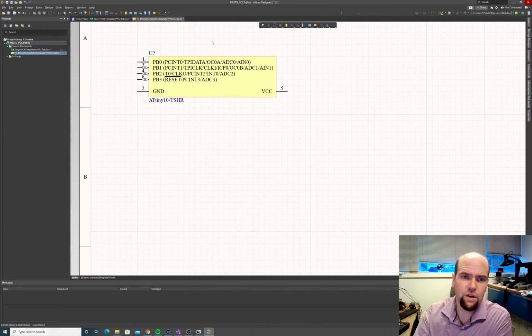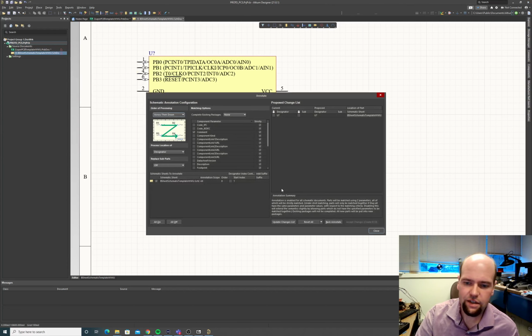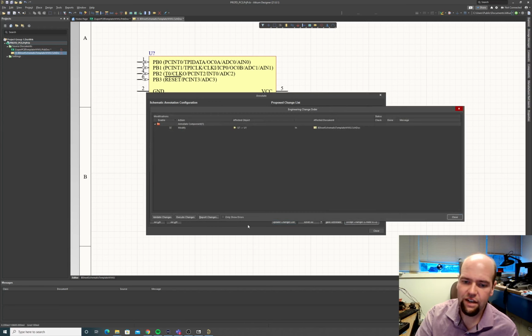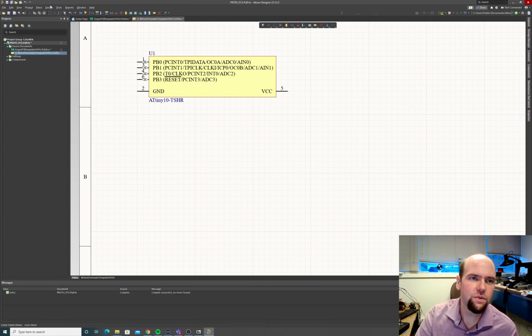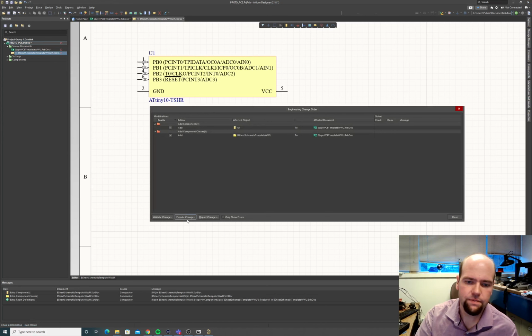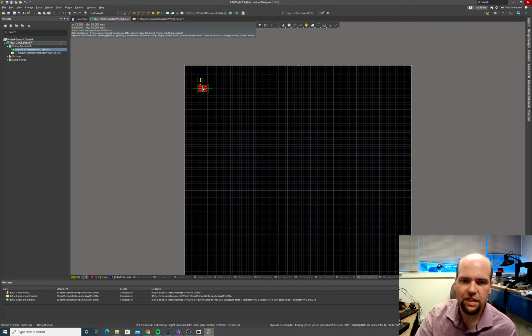And probably what we're going to want to do is have 3 pins on each side, which is typical. We could have 6 pins on one side. I'm guessing this footprint, actually I want to see what this thing looks like first. So I'm going to just annotate it. And actually there's a quick annotate in Altium now. So we do that, so annotated is U1. We'll do design, update PCB. Okay, so here's our part. Yeah, so it's a little 6-pin thing.